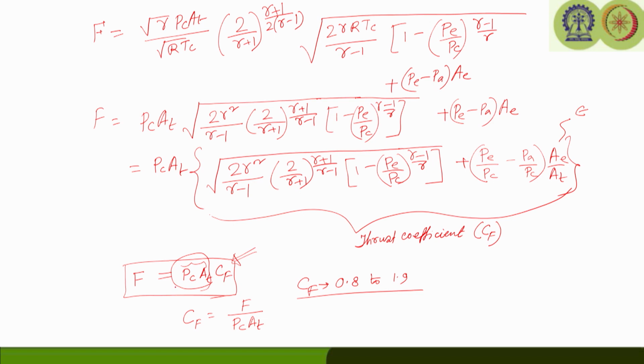Now, to understand the effect of chamber pressure, the altitude variation in a nozzle configuration, or to correct the sea level results for flight altitude conditions, it is very important that we consider this Cf. It is convenient to use this thrust coefficient parameter.